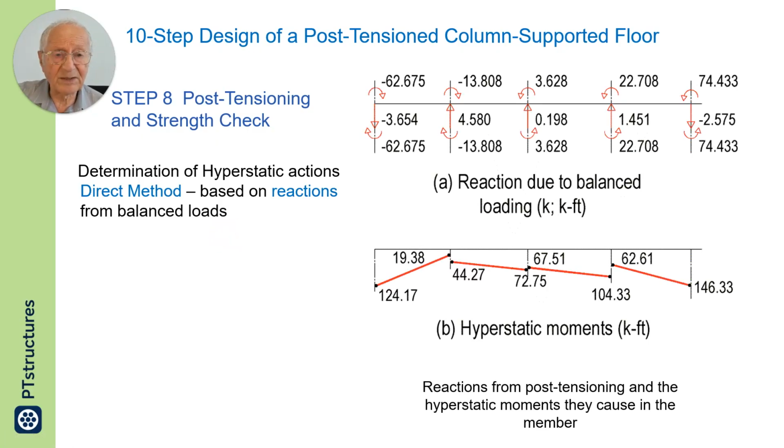In the direct method, you calculate the moments, hyperstatic moments shown at the bottom here, directly from reactions of the post-tensioning. Diagram on the right shows the column reactions and column moments.